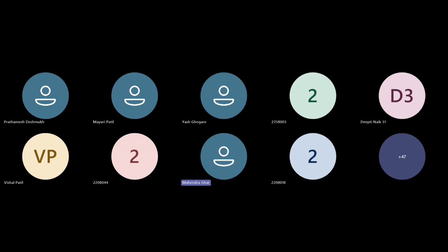See, majorly, one thing is what input voltage and output you need from the device point of view. For the practical aspect, to implement the hardware, you can use higher voltage and higher current switches directly. But maybe the problem is that the gate pulses you are giving are not able to drive your switch. That is one problem.